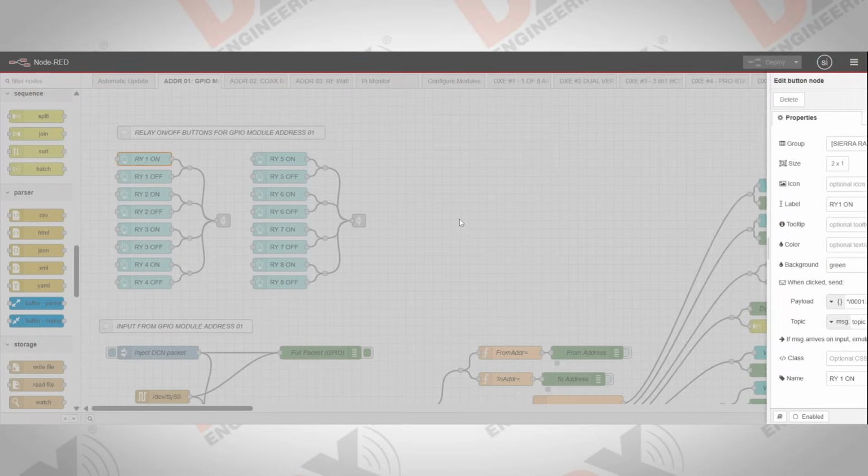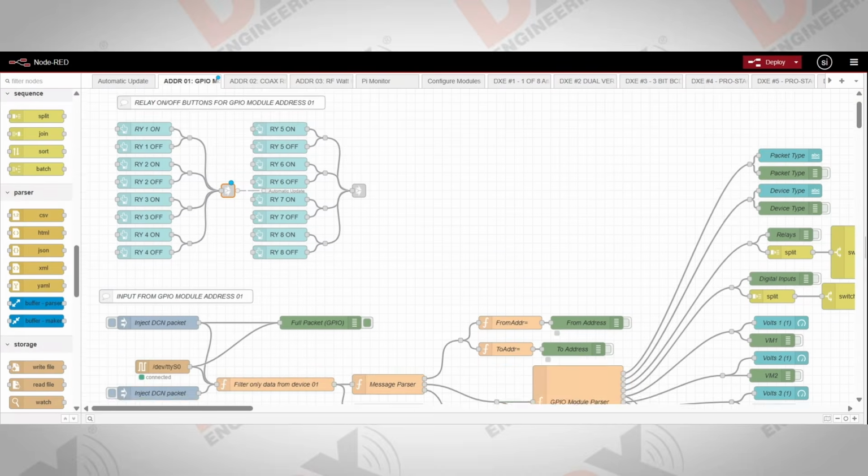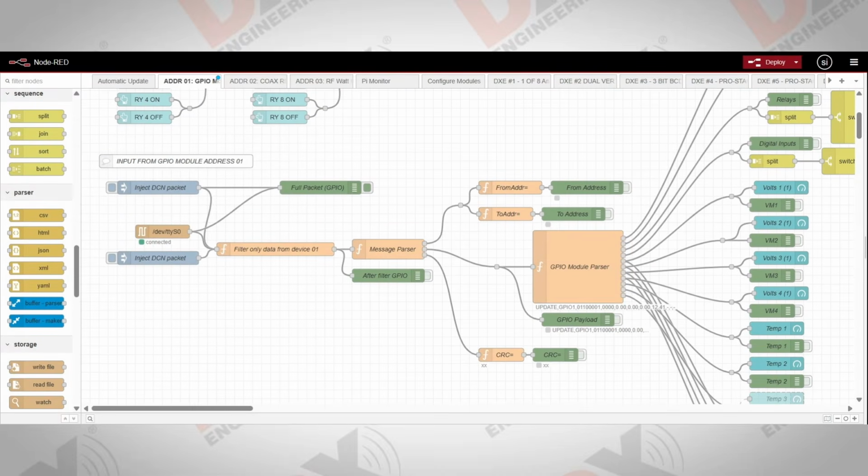Now, cool. And where this connector goes, by the way, this little square with the arrow, that's just a shorthand to say that the data goes to the part of the program that sends the command out of UART, and it is that simple. The rest of this stuff that looks much more complicated is more complicated because this has to decode the packets coming back from the module.